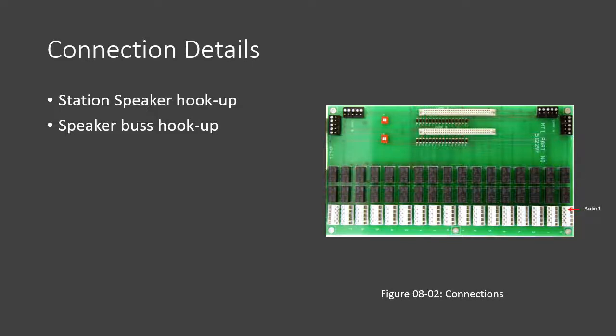For the staff stations, just like with your 81129, you have the same audio 1 and 2, or audio plus and minus, your call in plus and your call in minus, and then your shield at the very end there. Remember, the shield should be connected at the termination board but left unconnected, cut back and taped off at the field side.